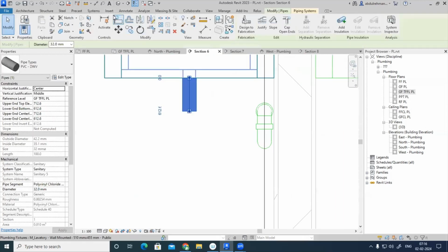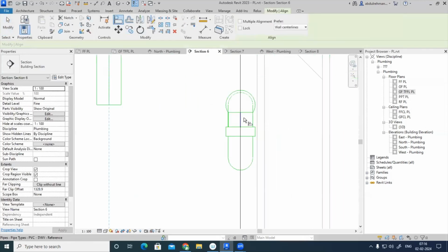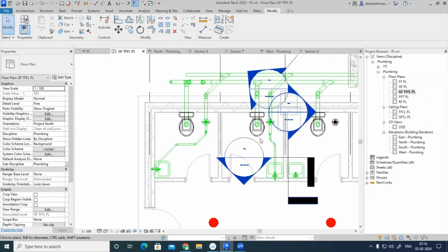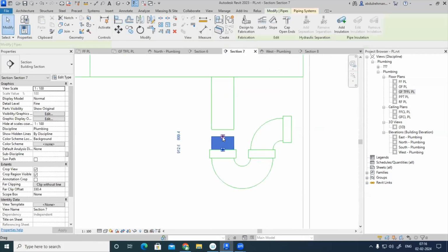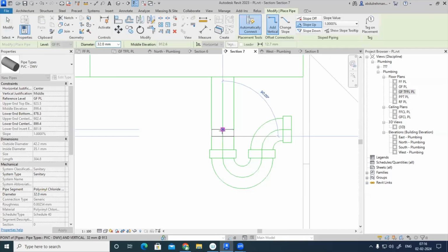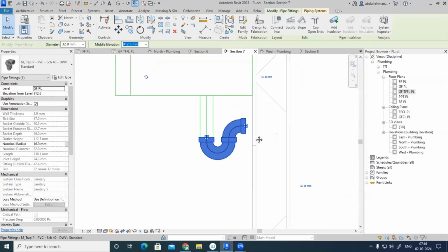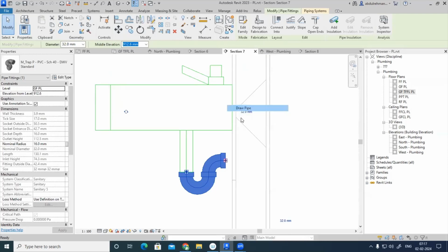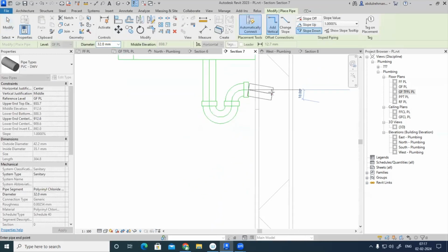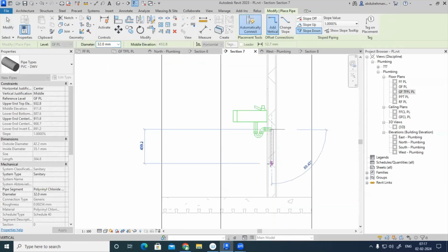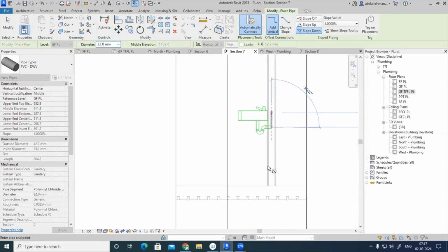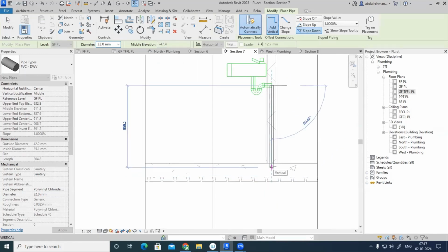Now align this. So now we can connect it here. Now just select it, right click. Okay. From this point, right click, drop pipe, slope down only. You can take it down. Venting also we have to do from this point. Circuit venting we have to do there.